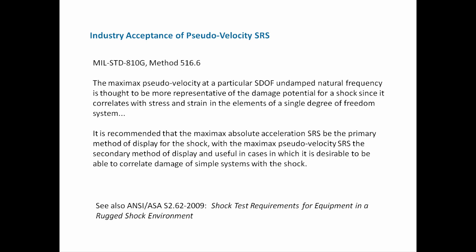And of course, getting the MIL standards to change, I mean, we're talking paradigm shift here. So MIL-STD-810G says the maxi-max pseudo velocity at a particular single degree of freedom, undamped natural frequency, is thought to be more representative of the damage potential for shock, since it correlates with stress and strain in the elements of a single degree of freedom system.